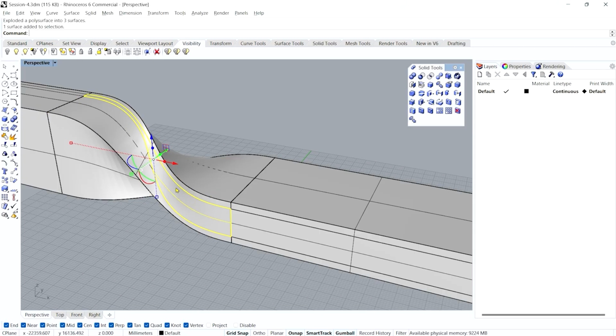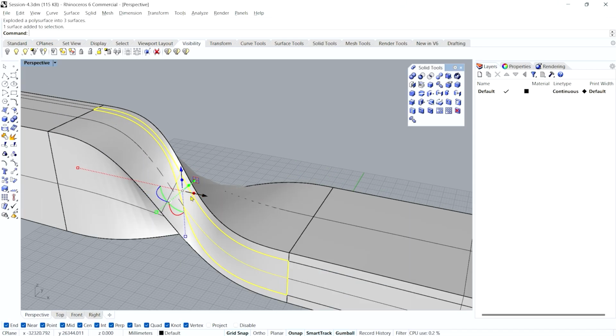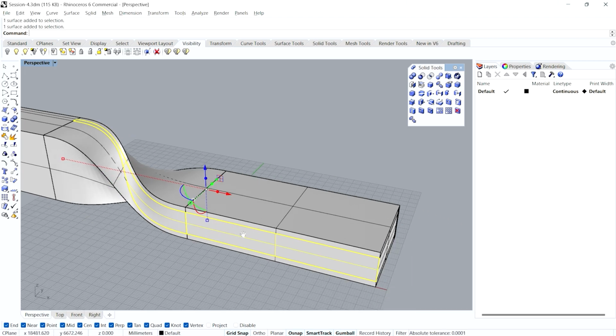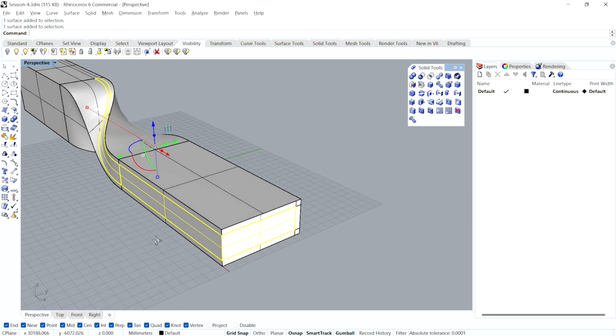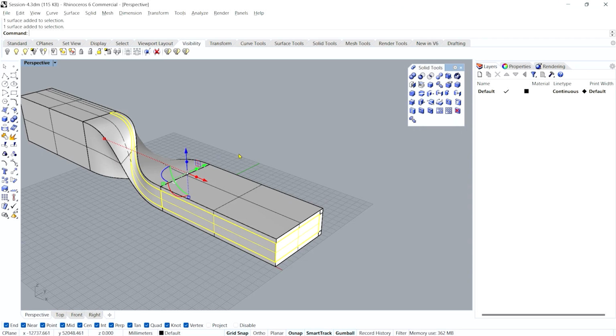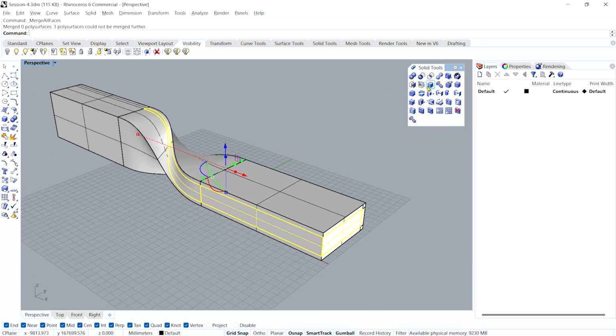So you have this glass which is blending like this on this particular twist and then which is continuing to this and this. So either you can join these faces or you can merge using this merge or coplanar, or you can join using the join command, JOIN spacebar. Now they are joined. They are one single glass element.